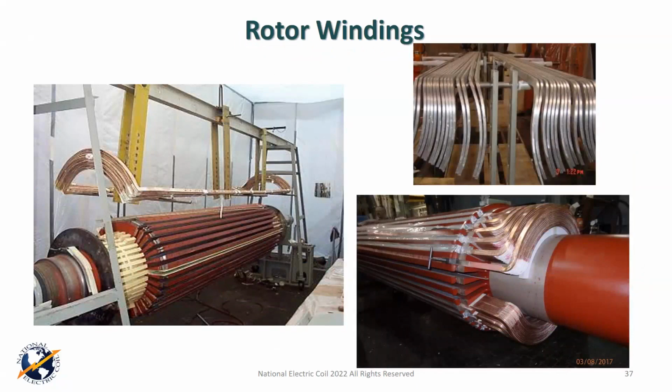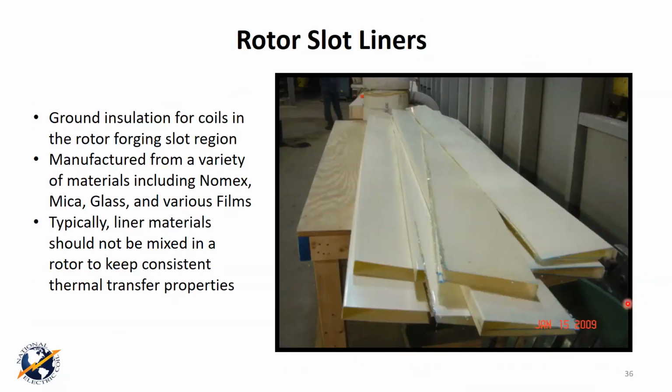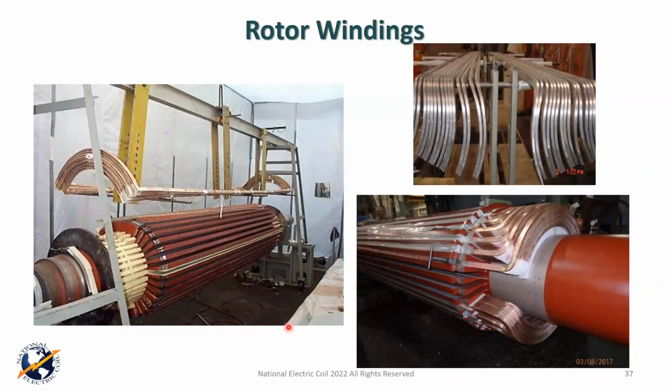All right, so going back to the rotor here, we've got the slot liners and we've got the forging. Now we're going to put this stuff together, and this is inside the shop. You basically have the forging here. Usually there's some temporary blocking that's used, and this is an assembly aid. Sometimes it can be a glass laminate or a G10, G11. It could be old micarta. Maple is a very common thing. I think that's what you're actually seeing here.